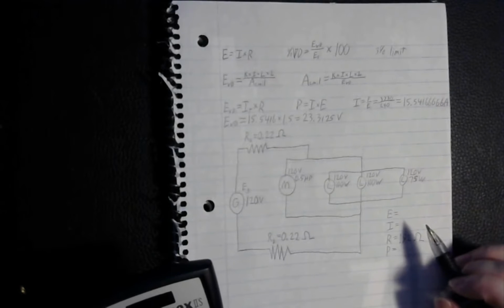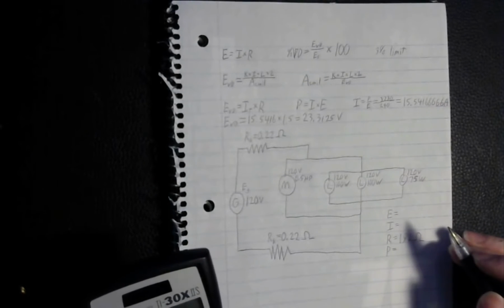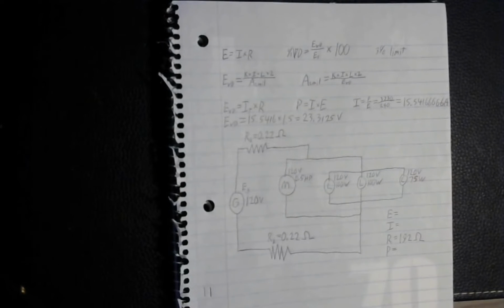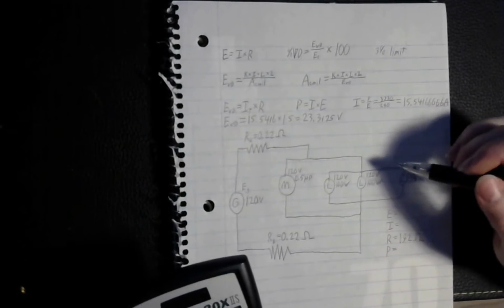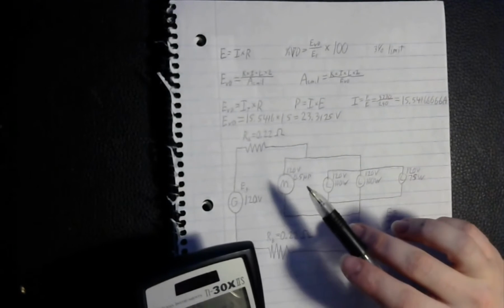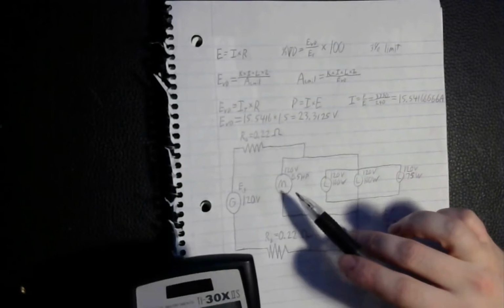And, oh, you know what? I just realized I do need to calculate the resistances of the others to do the rest of this. So basically you're going to do that same thing to figure out the resistance of the other two lights, figure out the resistance of your motor, and then from there what you can do...